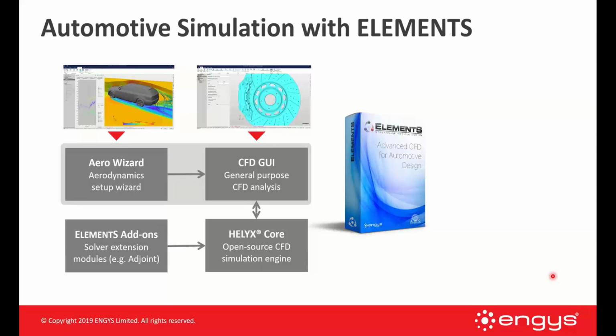Or we're able to obtain information about the external flow and give information about sensitivities on the surface. Where should we push in or pull out on a surface to reduce drag or reduce lift or increase lift, or whatever we need to do to control the flow. So it augments our decision-making capability.